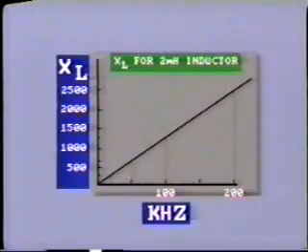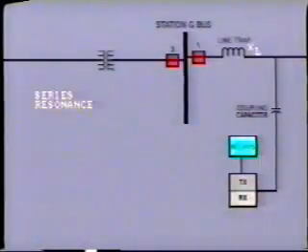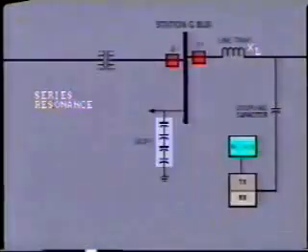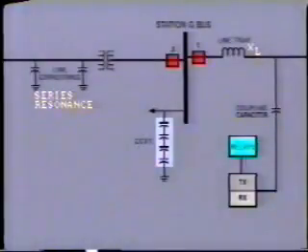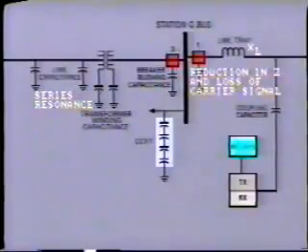You can see that this simple, untuned line inductor does offer a reasonably high impedance over a wide range of carrier frequencies. However, experience has shown that in certain installations, the inductance can create a high-frequency series resonance with capacitive circuits on the bus side, such as CCVTs, lines, transformer windings, and breaker bushings. The consequence of this is a drastic reduction in impedance and loss of carrier signal.